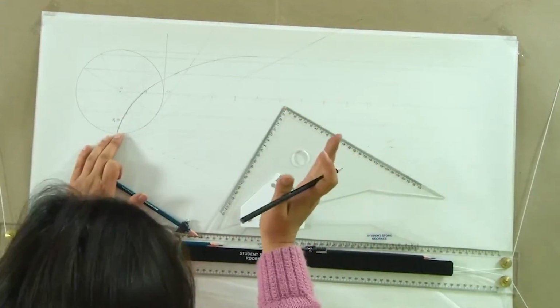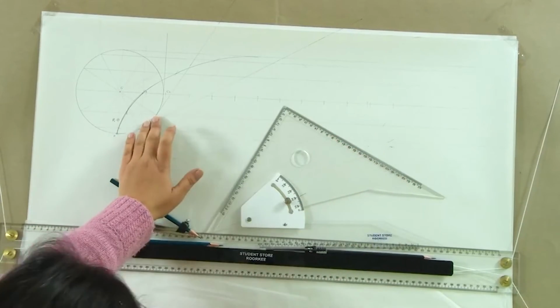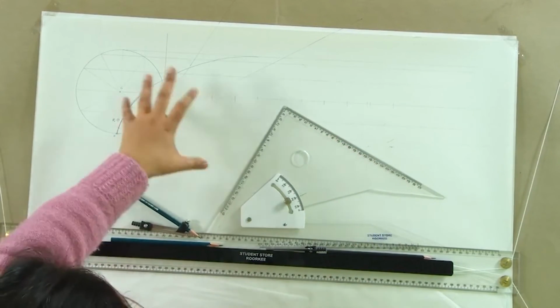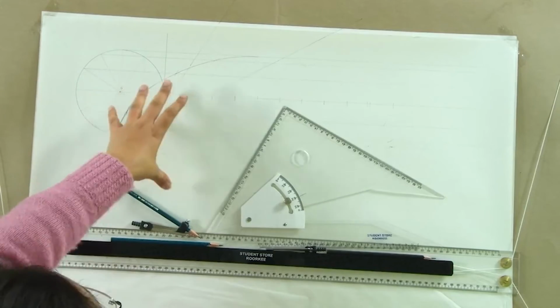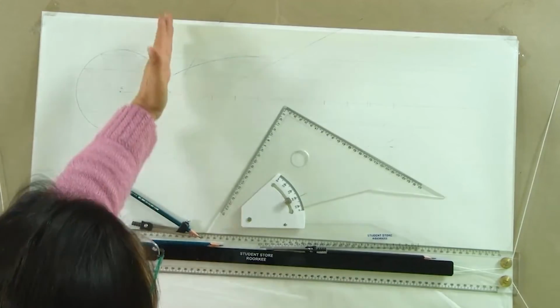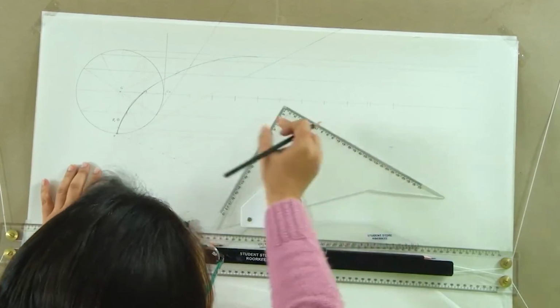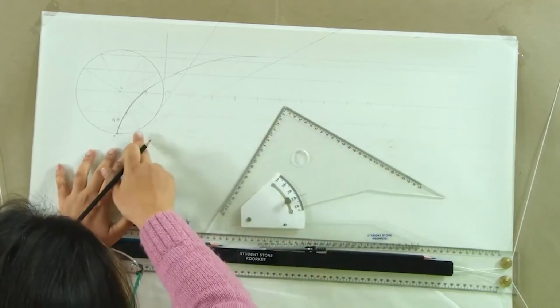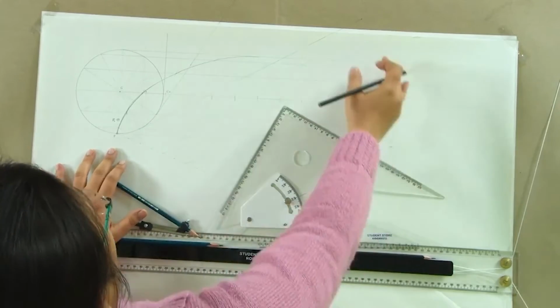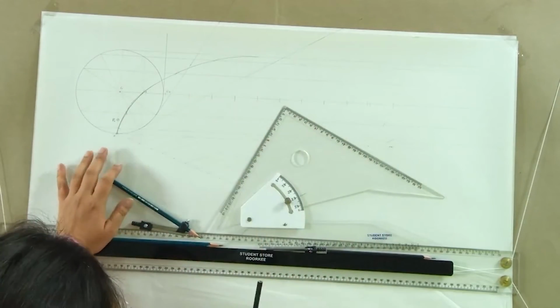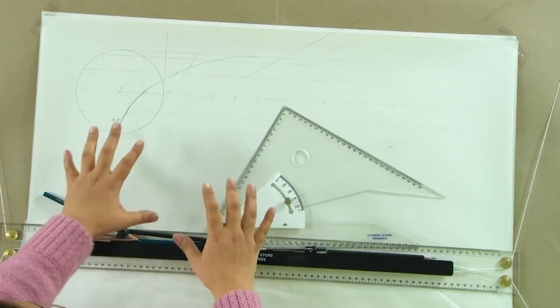In a circle it is easier to know what is the tangent, but in a square we would just be extending the side of the square on which we would cut the length equal to the leftover perimeter, and that is how we would get the involute. So, I hope it is clear how to draw the involute of the circle and square, and following the same process you can draw the involute of any 2D object.